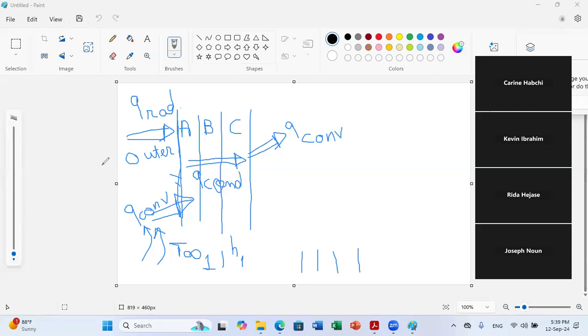Okay. Then in this case, to be able to study the effect of your envelope, you need to develop a mathematical model which will allow you to solve for the temperatures at different nodes of your system by a simple method. So first, you just have to say, I want to write an energy balance for my system. And what is the energy balance here? How can we write the energy balance in this problem?